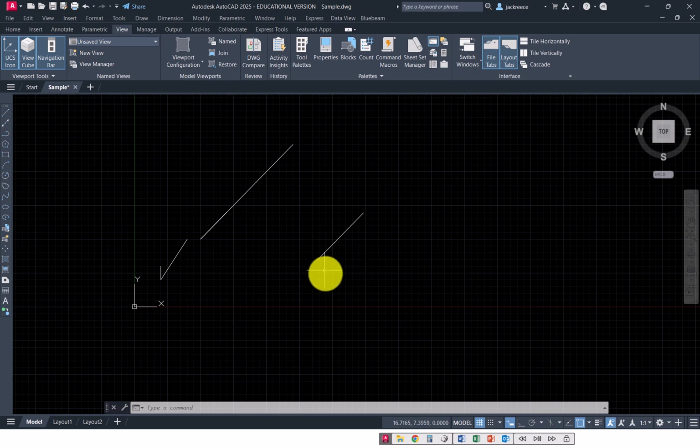If you want the line to come down, I'll demonstrate that one again. First point, let me pick that point. I'm going to say a distance of 5, tab, minus 45 degrees. It didn't do it. I don't know if I had my snap or what, but a negative direction would bring it down. Let's go into that again. 5, tab.